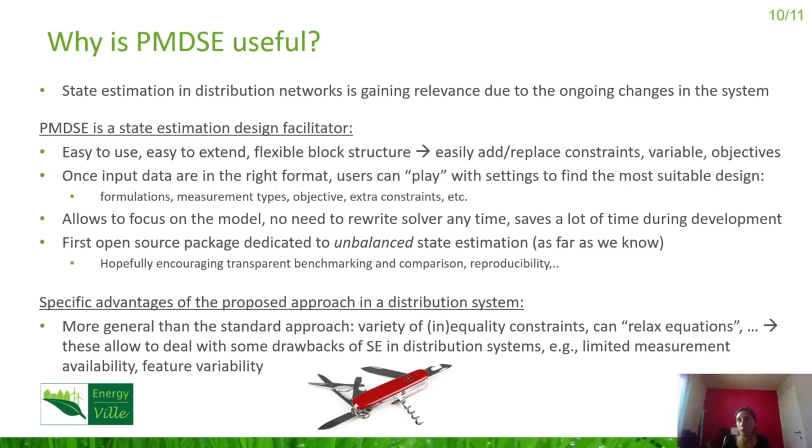And as far as we know, we're also the first open source package dedicated to unbalanced state estimation. Unbalanced means that we use three-phase power flow equations, which are needed to accurately describe unbalanced systems such as the distribution system. We hope this package can also be used as a framework to benchmark and compare different state estimation formulations and models, therefore increasing, hopefully, reproducibility and transparency in the realm of state estimation.